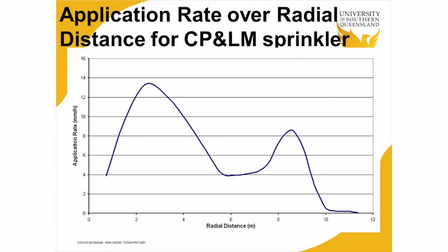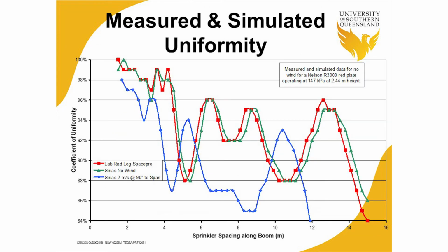And so you can imagine that's a troubling process for some, but the reality is when you actually take the time to do these things, you start to learn about the uniformity measures and the understanding of how the sprinkler spacing, as a simple thing on centre pivots, can actually impact grossly on the uniformity. Centre pivot packages and sprinklers are very expensive components, typically costing say 10% of the machine itself, but we've always said that they probably represent somewhere between 40 to 50% of the variability that can occur in a system. So getting the sprinkler packages right is quite important.